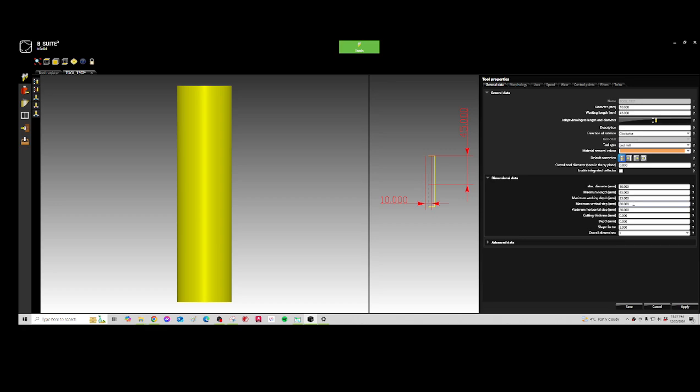Let's say this is a 10 mil, it's small. But let's say this was a 20 millimeter bit, and you want to cut 25 millimeters at once. You could, but for 10 millimeters, I don't recommend. So I'm going to put 10 mil at a time.